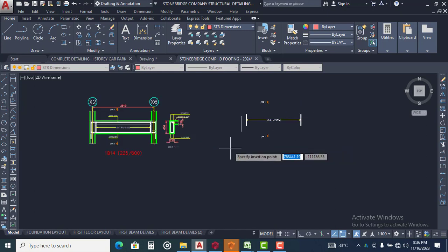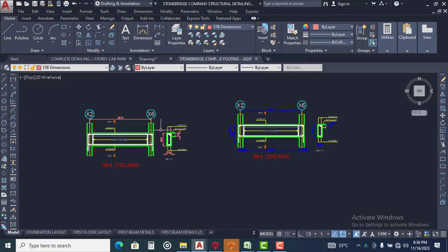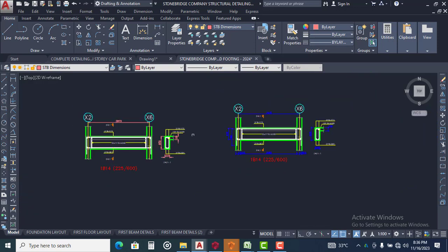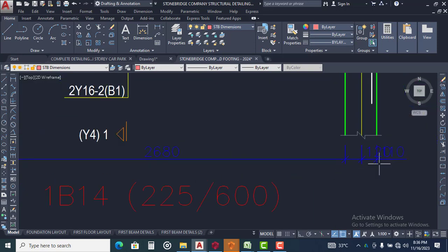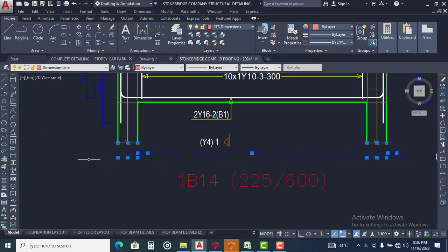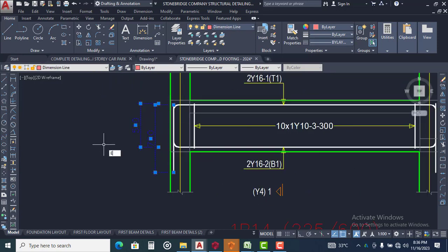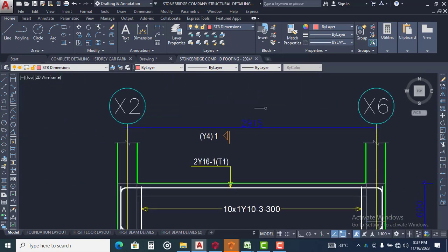So if I paste this, as you can see right now, this template helps to optimize your drawing from what you have here to what you have here. Despite that you have pasted it here, you just have some little work to do, which is just to remove what is not needed. Looking at this right now, you will see that this dimension here is not needed because Prota Structure tries to bring some things which are not needed, so you just have to remove it from the drawing.